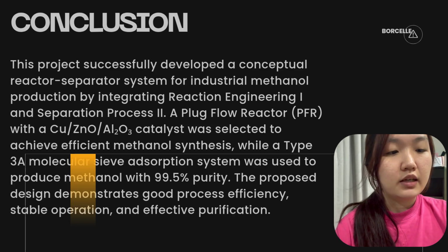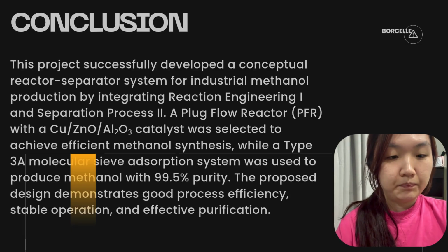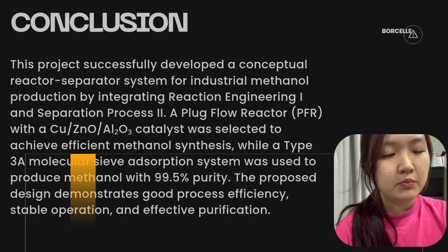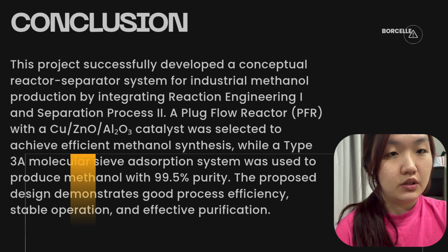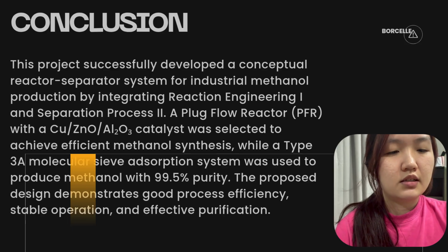In conclusion, this IDP project successfully developed a conceptual reactor and separator setup for producing industrial-grade methanol. By blending ideas from reaction engineering and separation processes, a PFR with copper, zinc oxide, and aluminum oxide catalyst was picked for methanol synthesis because it offers strong conversion efficiency, better thermal handling, and it also works well for continuous industrial production. The chosen operating conditions keep the reactor running steadily while still delivering the targeted methanol production rate and reaching a satisfactory level of carbon dioxide conversion.